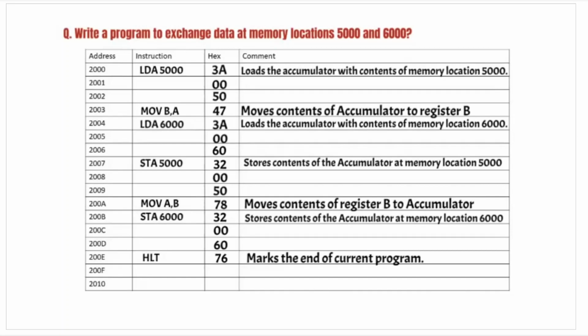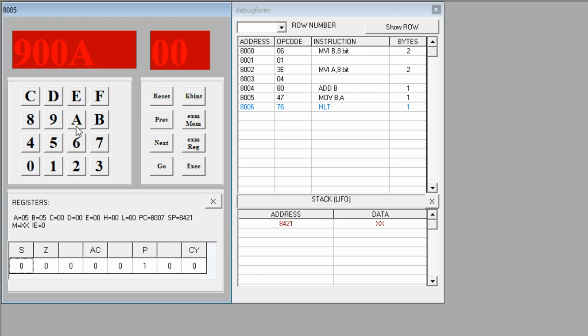Click on next. Then enter the least significant byte of your address. Next, and the most significant byte. Next. Now we are at 9008. That was originally 200A. So whatever was now in B, transfer it back to A. For that, I have the opcode 78.